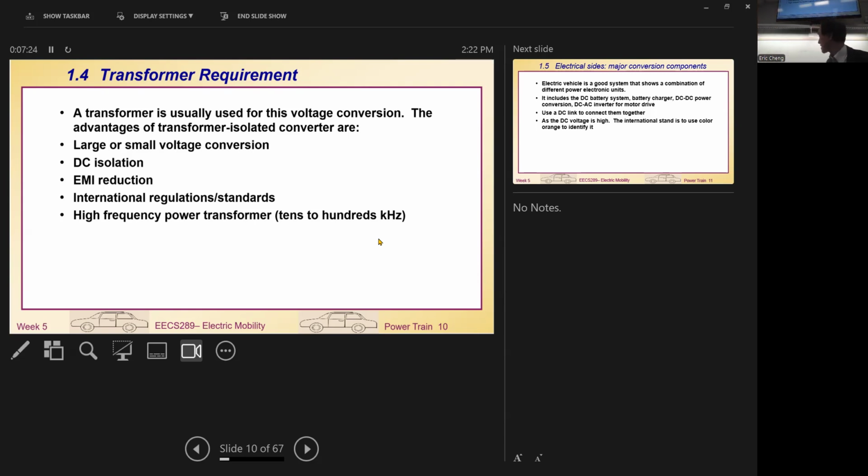So basically, for instance, you have the AC side here, a possible transformer here, then in here we may have some converter, or maybe a charger. One thing is, in here this may create a pulse current. Then this pulse current may transmit through here back to the source, and you would make the power source become dirty.